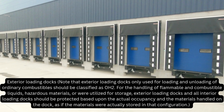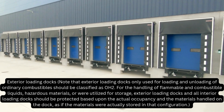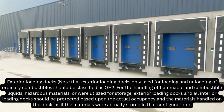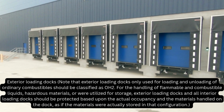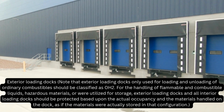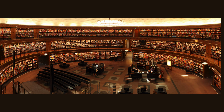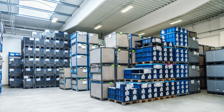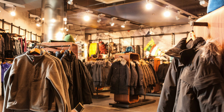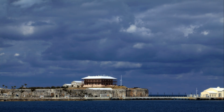For the handling of flammable and combustible liquids, hazardous materials, or where utilized for storage, exterior loading docks and all interior loading docks should be protected based upon the actual occupancy and the materials handled on the dock, as if the materials were actually stored in that configuration. Feed mills, horse stables, leather goods manufacturing, libraries, large stack room areas, machine shops, metalworking, mercantile, paper and pulp mills, paper process plants, piers and wharves.